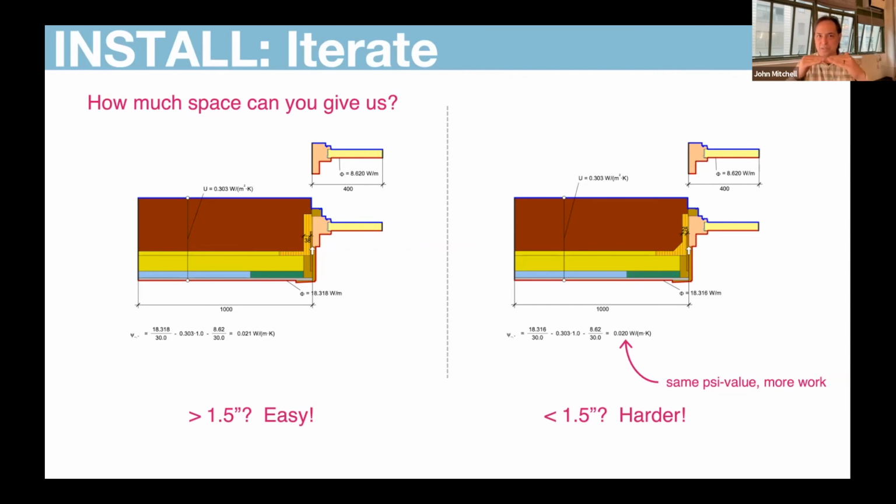I mean, ideally, those things would be just right together, but we can't do that because the window needs to sit where the window needs to sit, sort of out towards the edge of the building, and the insulation layer is on the inside where we have an opportunity to install it. And so we have to sort of bridge those two elements. We have to connect that interior insulation to that window, that window that's sort of out of plane with it. And we do that by insulating sort of up to and around the frame.